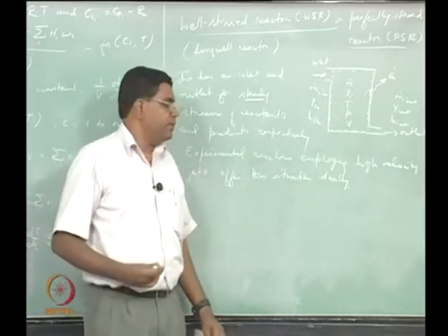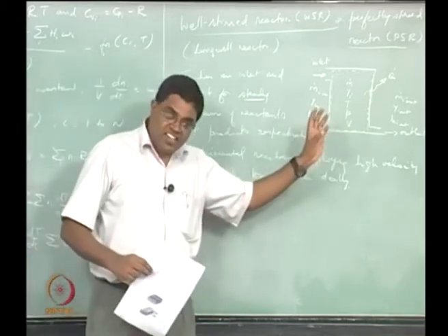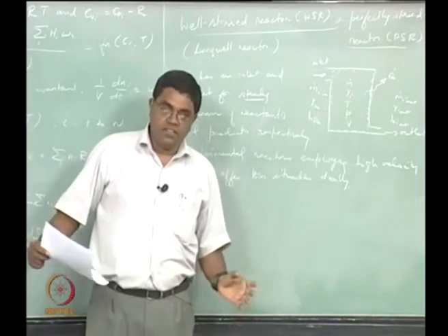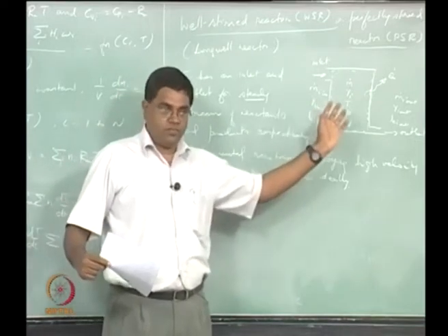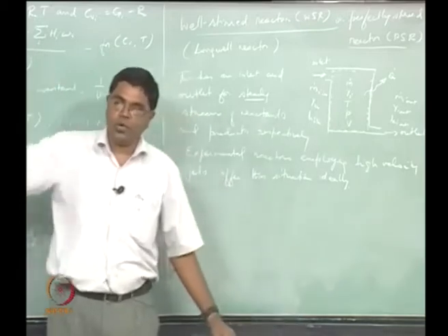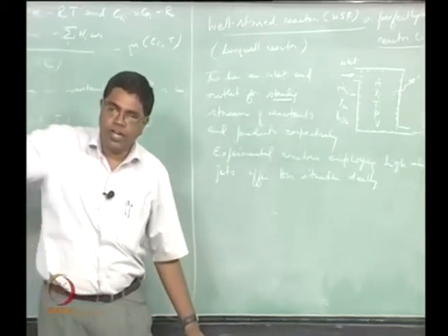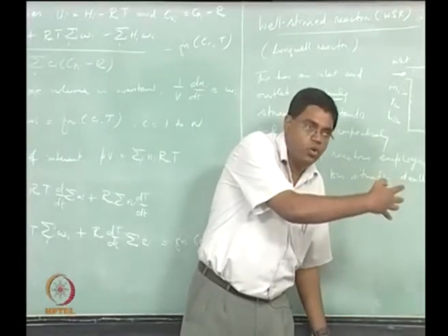What we will also see is typically this is used to design reactor sizes like the volumes, based on another idea of what is called residence time. So essentially what happens is you now have a reactor and you want to have a throughput of reactants coming in, reacting and producing products and that go out.